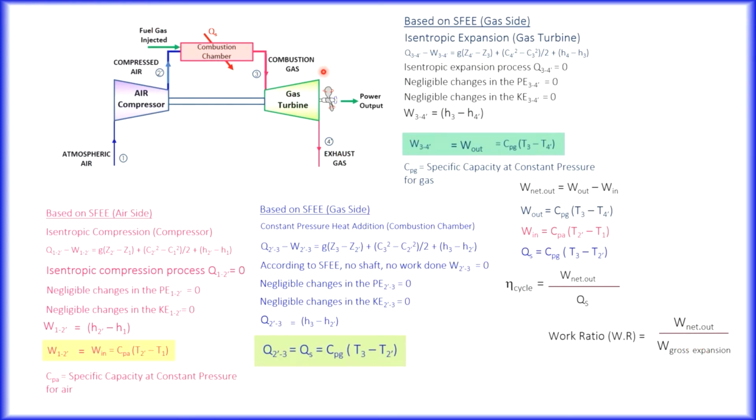When you look at the open gas turbine unit, the only part which gives you the gross is all the turbine work. If you have a series of turbines, you must add up all the turbine work to give you the gross expansion. Remember, a compressor is compression, so it is excluded from this term. Any amount of compressors, or any amount of work in, will be excluded. Net work out, as I mentioned, is work out minus work in, so therefore you can find the work ratio.